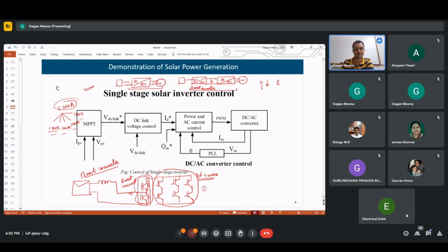If solar PV installation increases, during daytime when the peak solar is there, we can charge the vehicles. So that is one of the smart charging. If generation is more, charge the vehicles, because at that time, if generation is in excess, the price will also be low. So both A and C are correct here.